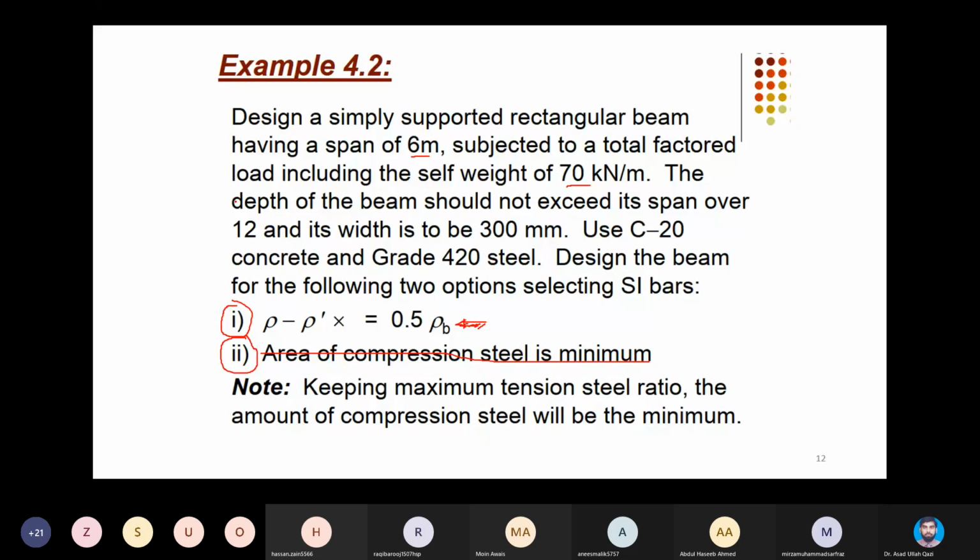And don't forget that when you estimate the load transferred on the beam, we did that estimation in the last lectures, and we divided the slab into trapezoids or triangles. What we were calculating was the weight of the slab only. That does not include the stem load, the projection of the beam below the slab. It also carries some weight, and that can be calculated by multiplying the cross-sectional area by the density of concrete, which I may call rho d, which is 2400 kg per meter cube. It will then give me the answer in kg per meter.